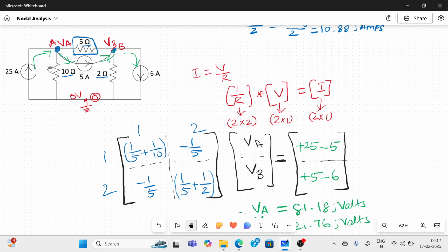If you have any voltage source, then that should be in series with a resistance. In nodal analysis, sometimes the problem will be solved with a voltage source present. Then the voltage source must have a series resistance to solve by the matrix method.